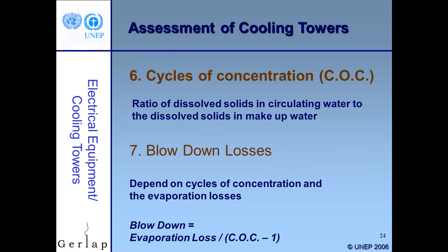But we'll see. And then there's also blowdown losses. This depends on the cycles of concentration and the evaporation loss. So the blowdown loss is the evaporation loss divided by the cycles of concentration minus 1. We'll get into these numbers later and in other presentations. Right now I just want you to at least read the definitions and have heard the terms.